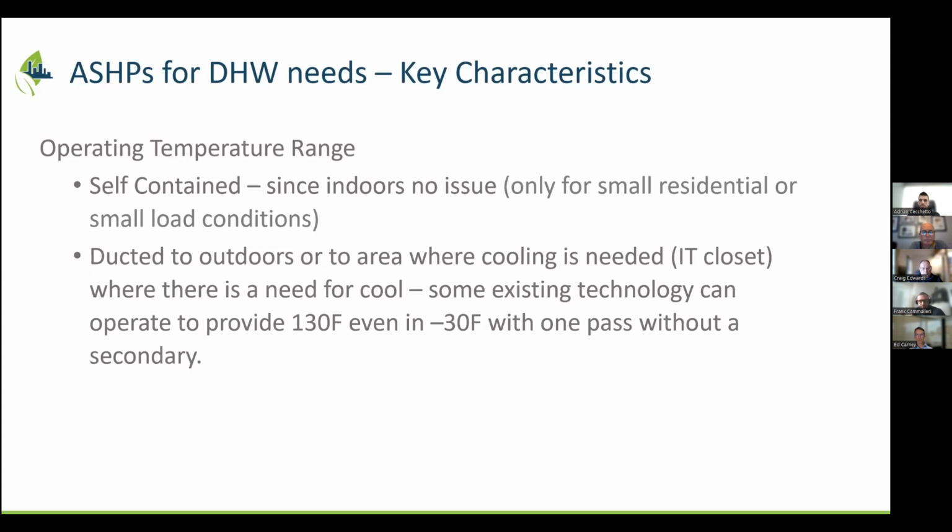There's an optimal amount of sizing that you do here. If you want somebody that really wants to do this all with heat pumps, well, yeah, you can spend a lot of money and put a lot of refrigeration equipment in to do it, even at those low extremes. But as we'll talk about in future slides here, it comes a point where it just becomes very expensive to put in a lot of these systems when you can have just a small amount of backup electric to trim on those hours that don't occur that frequently.